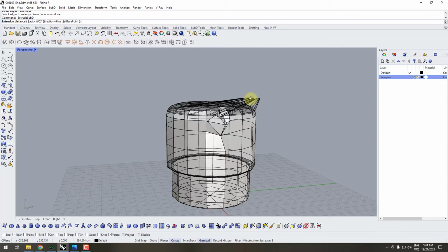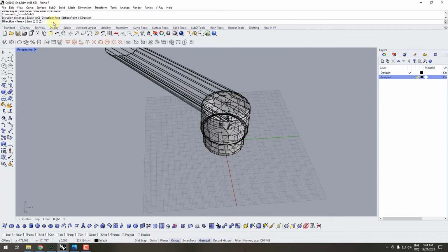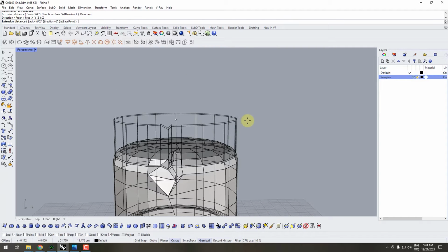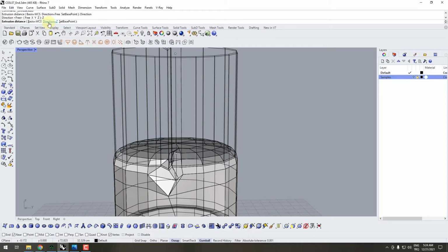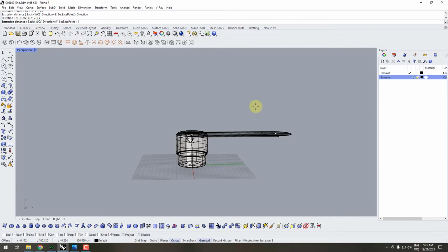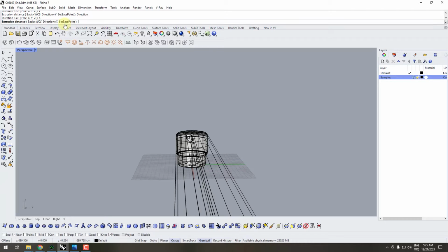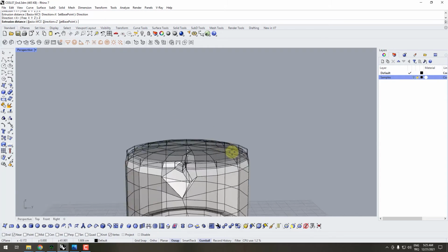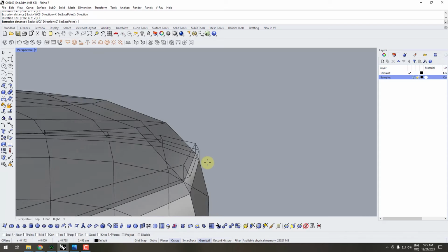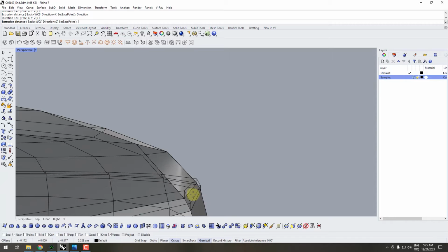Because of this, the surfaces are following our mouse, but if we set direction to, for example, Z, surfaces will only be extruded in the Z direction, or you can set it to Y or X. In this occasion, the Z direction can be considered suitable for our goal, but I want the surfaces to be extruded in the exact direction of the base surface.